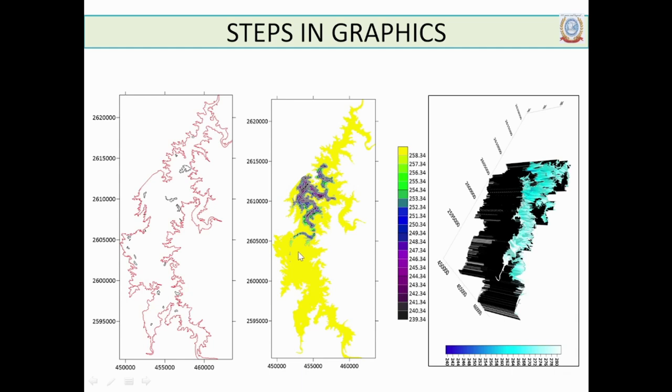In this particular case study, this is at Mahi Bajaj Sagar Reservoir in Rajasthan, where Nuclear Power Corporation is coming out with a power plant, for which they want to understand the deep zones and the path through which the pipeline has to be drawn. To get a powerhouse here, we need to find out the deep pockets. Then from superimposing the DEM over it, we could tell them the optimal path through which the pumping system, the pipeline, has to be routed to the powerhouse.